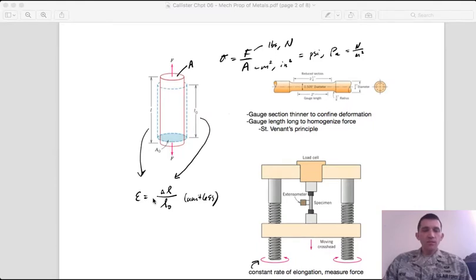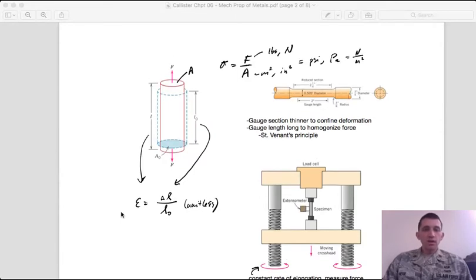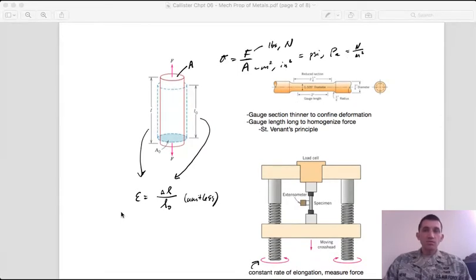And then for the strain, epsilon, here we don't want our measurement to be dependent on our choice of length for our sample. You can imagine that a longer sample to begin with will be able to stretch more, absolutely, as opposed to a relative sense. But we want to make sure that we're isolating the strain of an arbitrary sized piece of material, so that the geometry of our sample, again, is not included in our results.